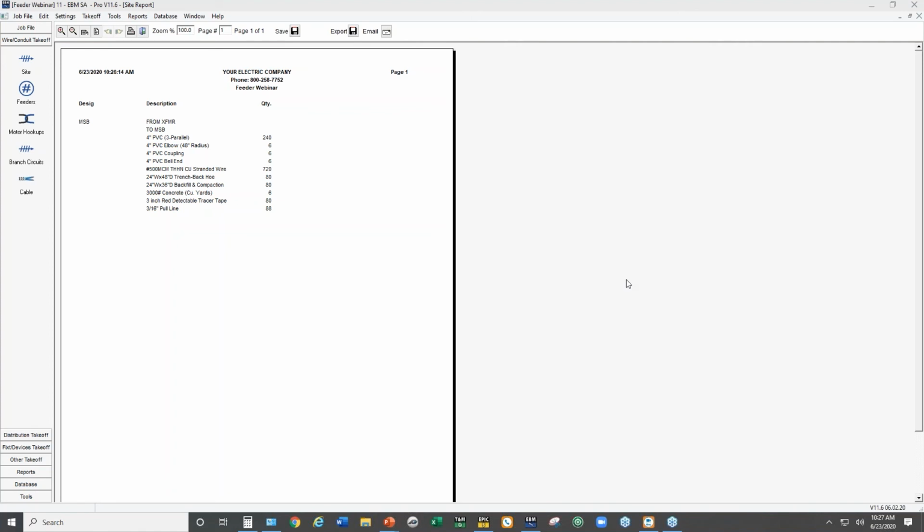So the question about adding fittings to the drop-down modules was, the materials that you want in those drop-down modules have to be somewhere in the database. So if you don't know where they are, you have to find them or you have to add them to the database. The second one, which is the tough one, is you have to use the attributes feature to assign it, and that's a whole other topic. It is pretty difficult the first or second time you do it, but there is a place in the setup in the database that you can assign attributes.